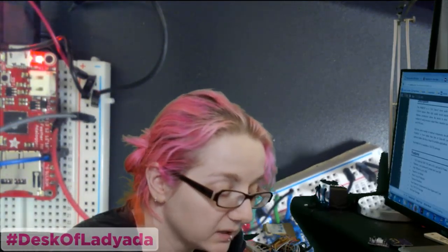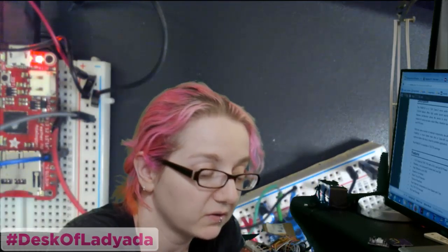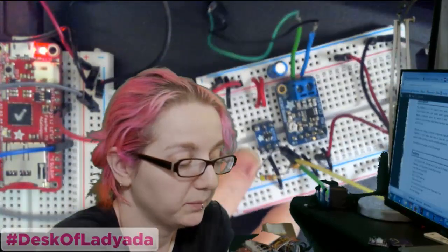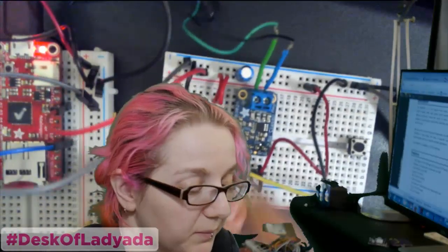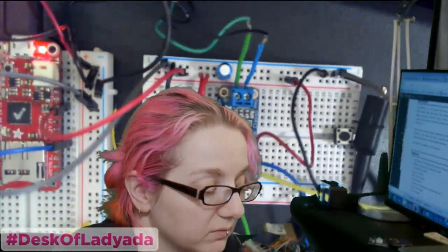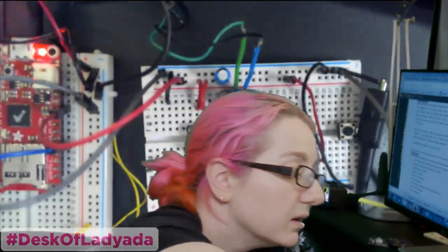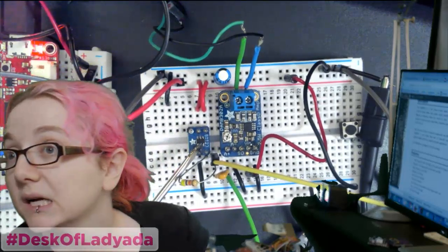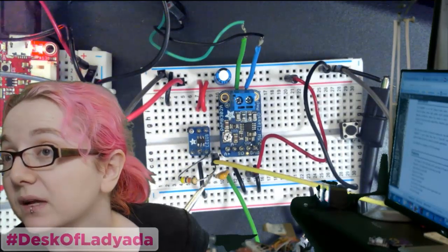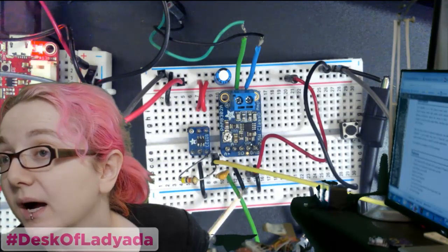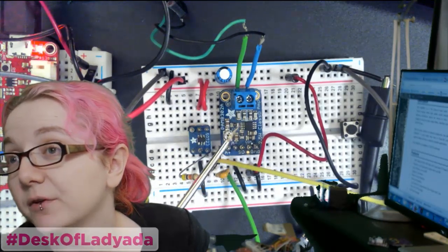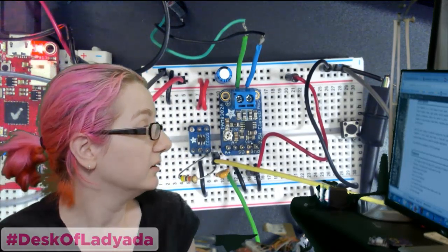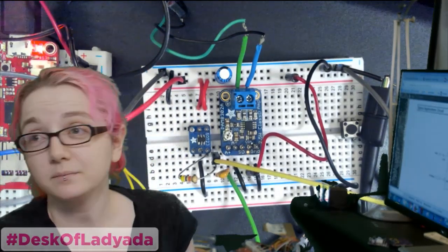And then over here, I have another little speaker, because I was comparing the two, and I just breadboarded up the SOT-23-6. I just breadboarded this little chip on here, and then I just added a couple of components, because it does need a capacitor. I basically don't have all the support components that I have here. So I just looked at the data sheet and wired it up.